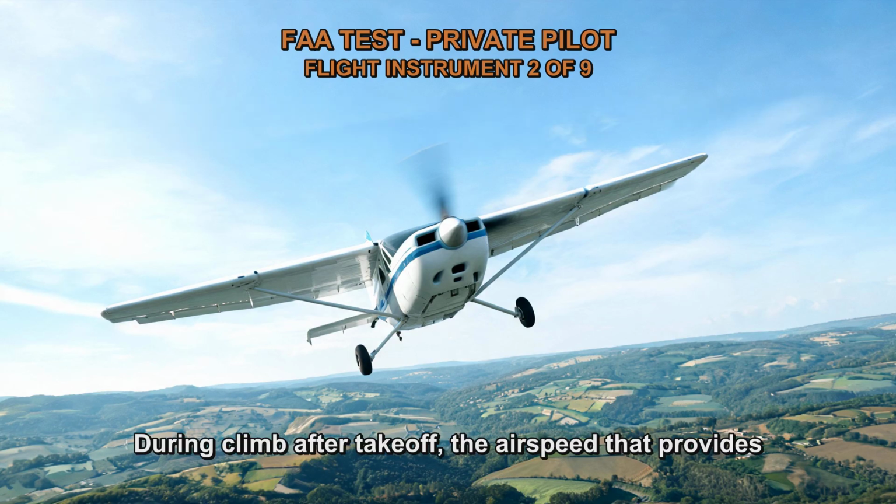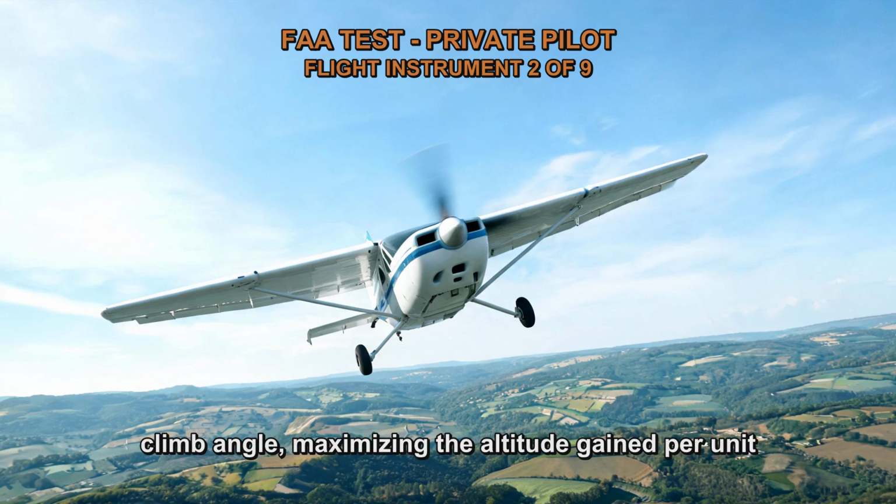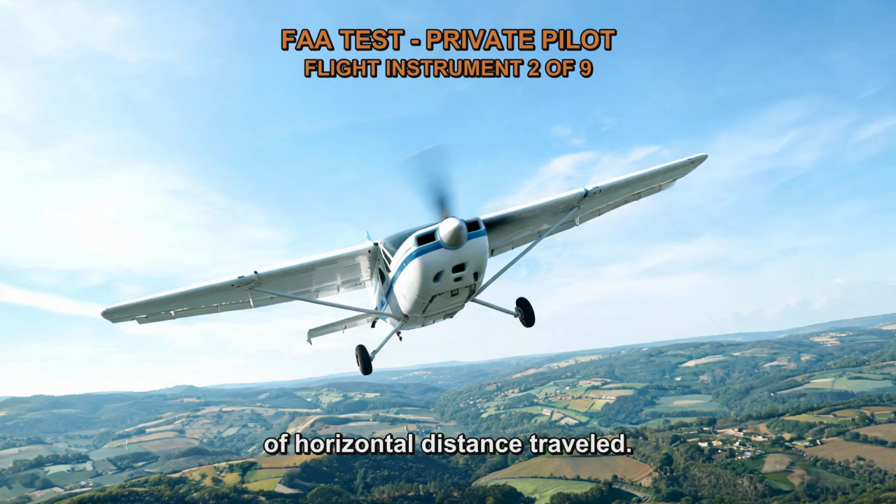During climb after takeoff, the airspeed that provides the greatest gain in altitude in the shortest distance is Vx, which stands for best angle of climb speed. Vx allows the aircraft to achieve the steepest climb angle, maximizing the altitude gain per unit of horizontal distance traveled.